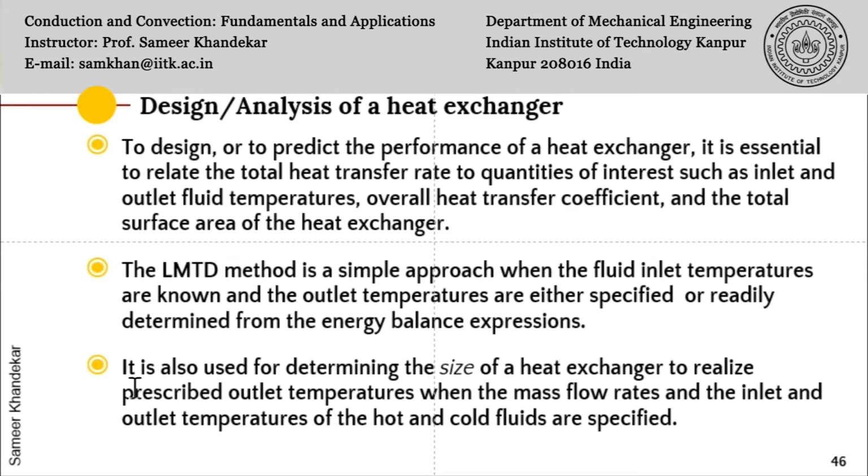Then it is also used for determining the size of the heat exchanger. That is what I am saying, sizing, to realize the prescribed outlet temperature. So for example, if you know the inlet temperatures and for a given size of heat exchanger, the outlet can be predicted. But then if that doesn't satisfy the client, then you need to increase the area so that there is more residence time inside the heat exchanger, and so you will get the desired outlet of either the hot fluid becoming colder or the cold fluid becoming hotter, whatever is the main objective function. You achieve that by the sizing problem. So this is how you will proceed.